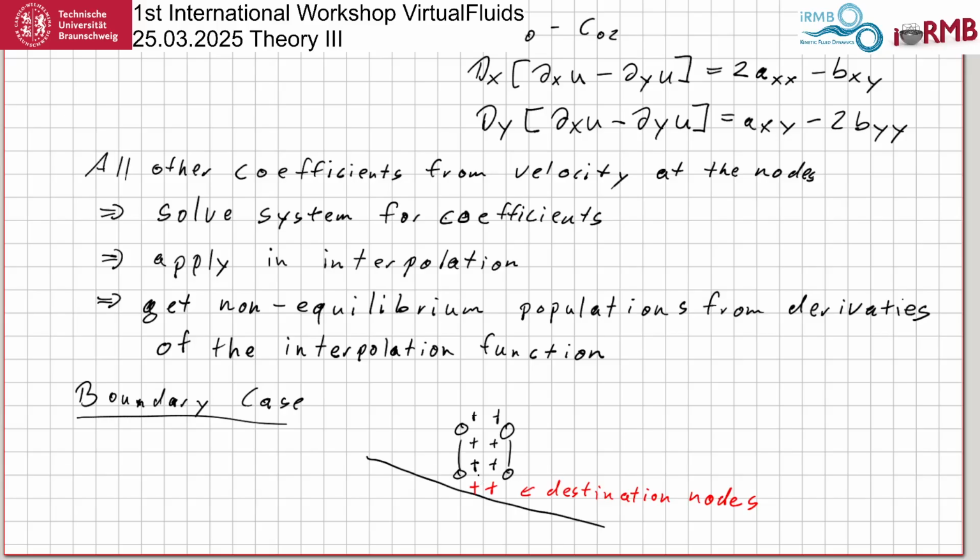So the very simple solution, and maybe that's not extremely accurate, but the very simple solution that is taken in VirtualFluids is to use an offset. And maybe that's not the best idea in the entire world. I was very skeptical about this and was amazed that it's actually stable, because all we do is use the next nearest complete cell and evaluate the interpolation function outside.